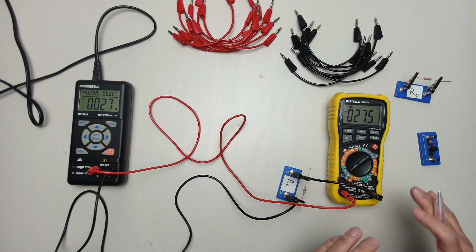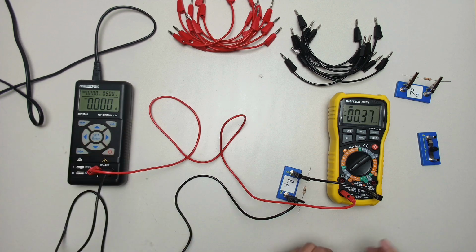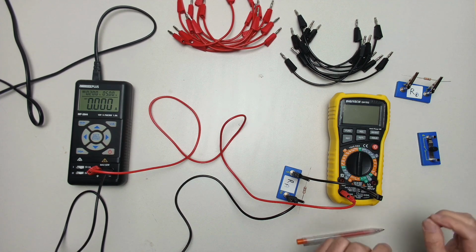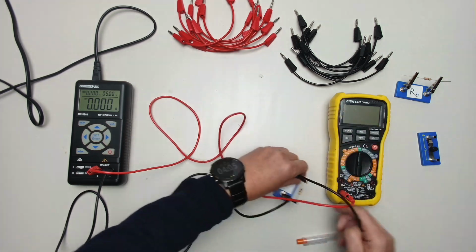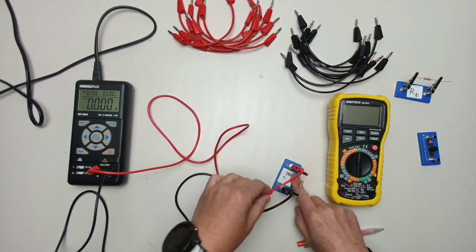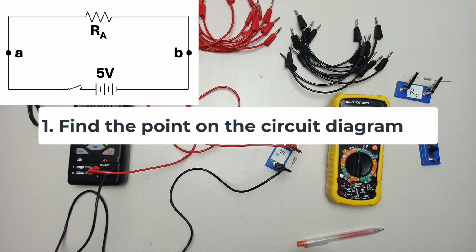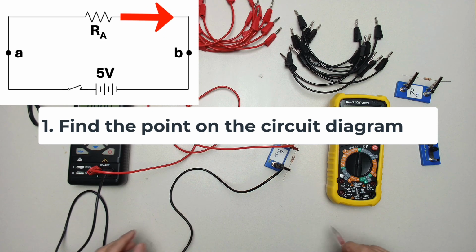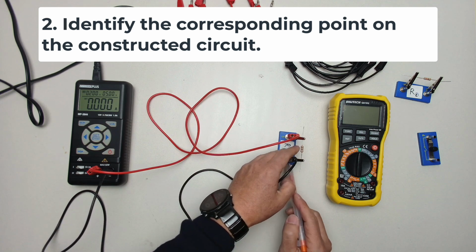After you finish the measurement of current, the most important thing is to turn it off. Turn off. Now, this is important because it's a good habit to put everything back to the default. And put this one back to here. So this is our default circuit. Next, we're going to measure the current after it passes through the resistor. So it means technically we can measure the current at here all the way to this point.